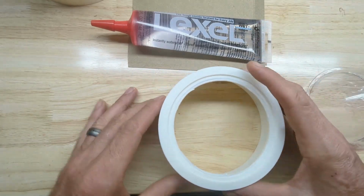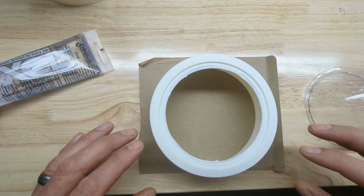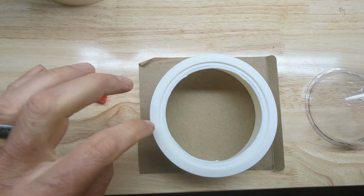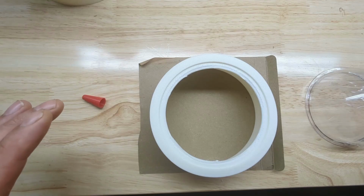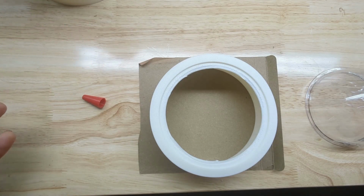So what we're going to do first, this Lexel is very sticky and messy, so definitely put your cap onto some type of table cover. You don't want to get this on your kitchen table or your workbench. What we're going to do is apply just a thin bead around the edge of this, and then we'll take our dome cap and seat it on there. Once it's seated, try not to move it. Let it start curing. Just set it off to the side and let it cure for several hours. I would even recommend not putting it on the body of the enclosure yet. Just give it a day before you do any kind of touching on it.